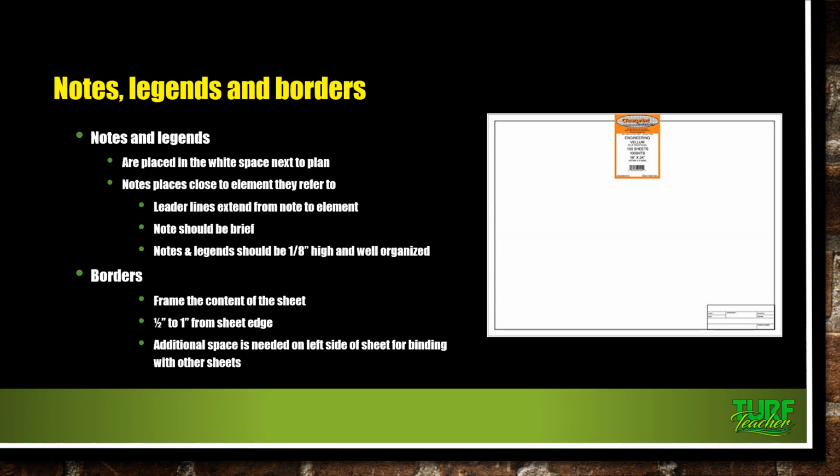Notes. Notes placed close to the elements they refer to. Leader lines extend from the note to the element. The note should be brief. Notes and legends should be 1/8 inch high and well organized if you're doing it in architectural lettering.